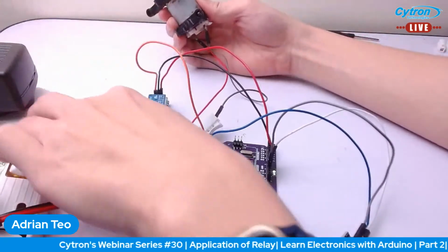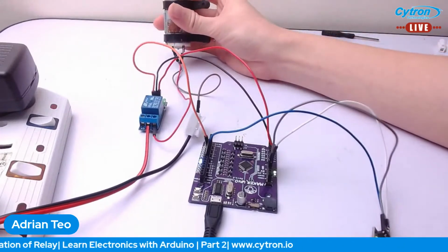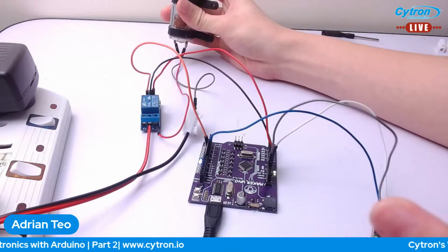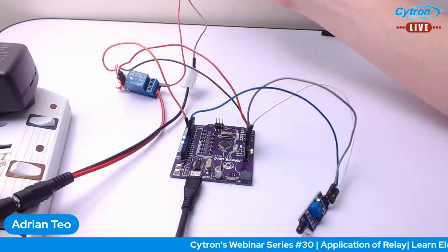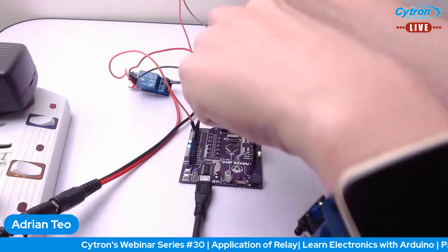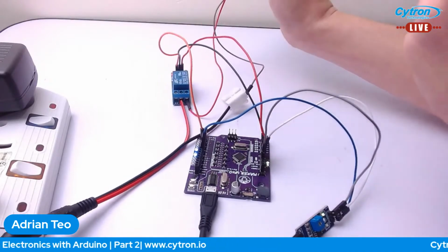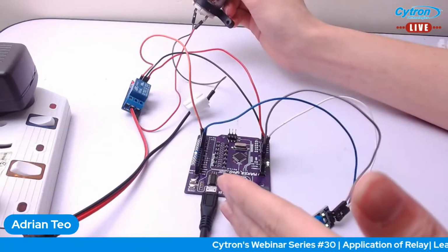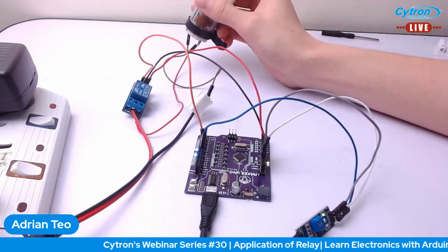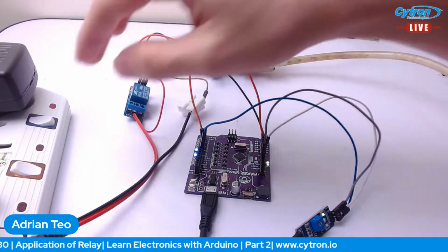Okay, last I checked, the pump is working, but again, the connection is the same. No water to demonstrate. The pump should turn on and then turn off when my hand goes in front of the IR sensor. But this is the connection here. 12 volt, enter that to the pump. My polarity is correct. Yeah, my pump is on right now. I don't know if you can hear it, but the pump is on. It's on, and then when I put my hand in front of the IR sensor, it turns off, and then it's on again. You can only hear vibration because there's no water to demonstrate.